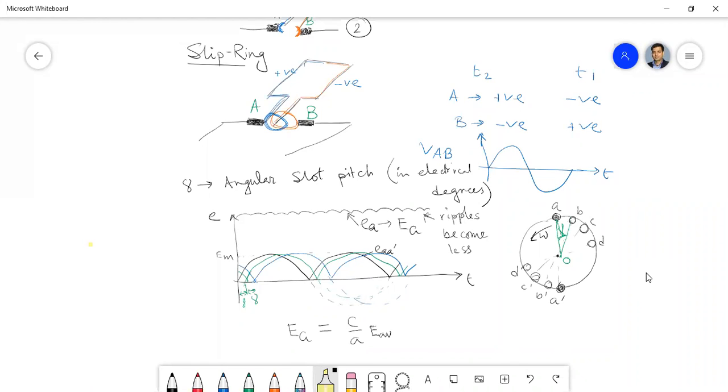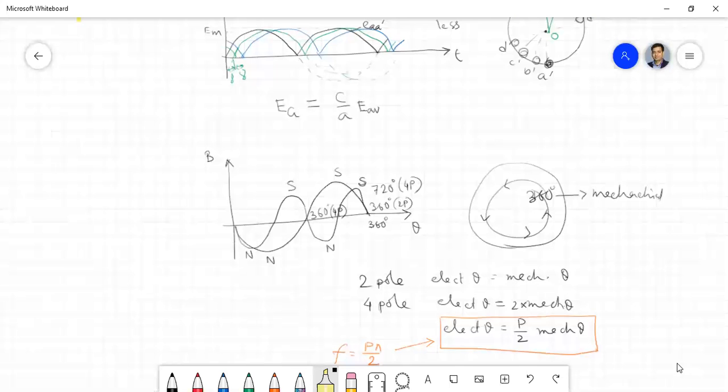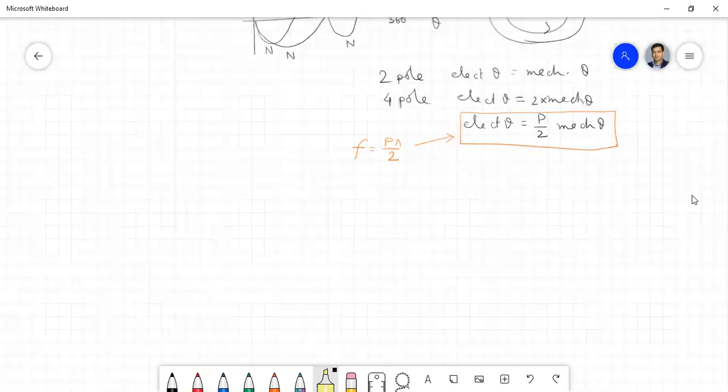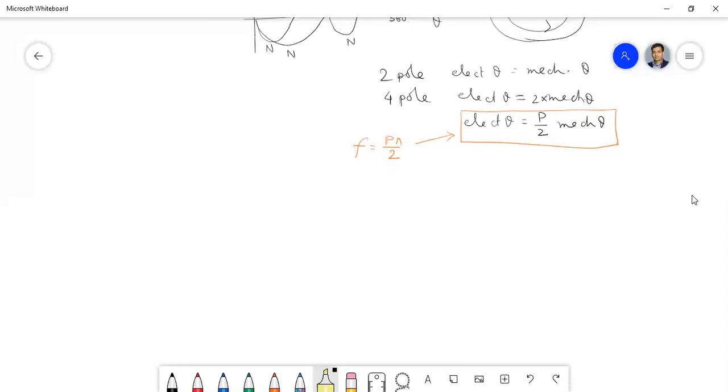How can we produce DC in the armature coil? Because in the armature coil we are not producing DC. We are giving DC. We are supplying DC. We are not producing anything. The link is through the brush only. Through the brush only. It's the other way around.